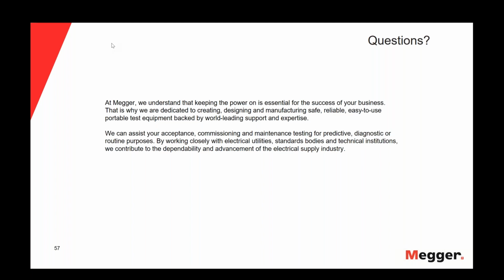All right, thank you, Robert. Henning, what insulation resistance minimum and maximum values will be considered as good cables in medium voltage cables? Well, when we talk about medium voltage cables, we have to differentiate between solid dielectric cables and there are still quite a number of paper insulated cables, which is the PILC cables. So you can say the solid dielectric cables, obviously the insulation resistance of a good cable should be in excess of 100 megohms at least.